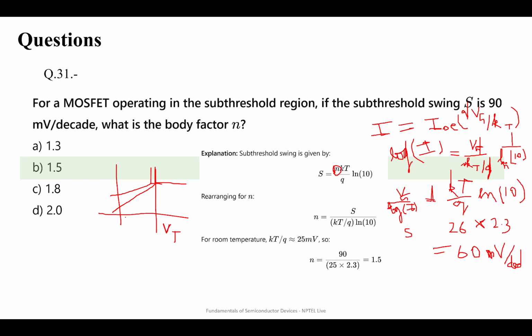But there is one way to go below 60 millivolts per decade, and that is tunneling. Nowadays there is research going on looking into tunneling channels where conduction is through tunneling, because tunneling is restricted by quantum limits, not thermodynamic limits.